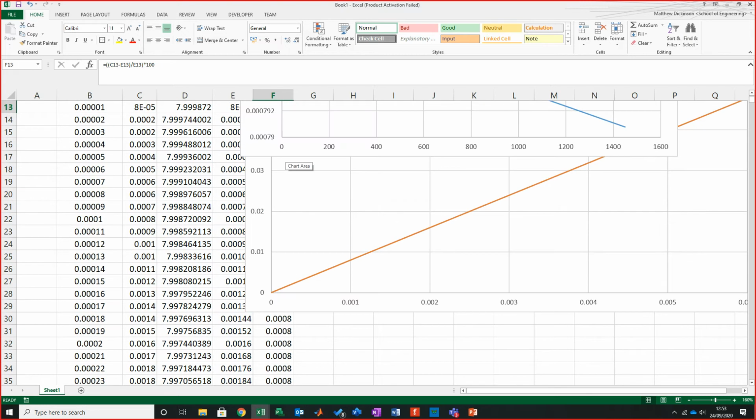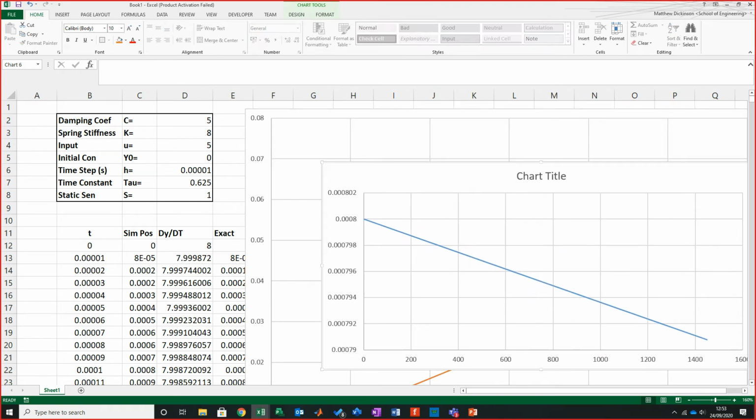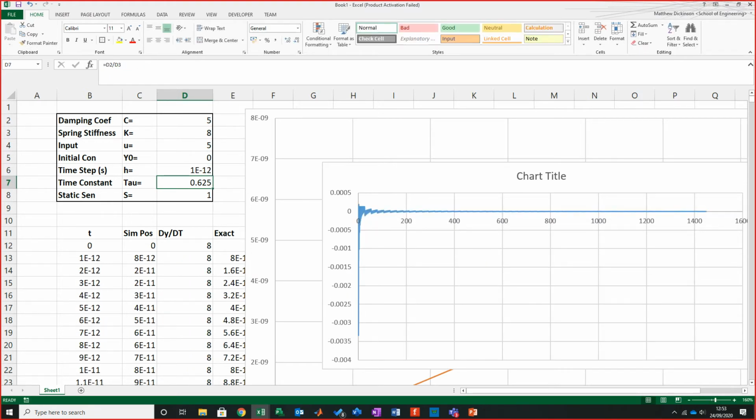So my point is, often when you're building a simulation, a system that you're predicting, a lot of people go, well, I'll make it, and in meshing this is the most common, okay, I'll go super fine. If you go extremely fine on a particular simulation, when you run it, what you'll actually find is it crashes. The amount of people I've seen sat there, and I'm not just talking students, who go, why is it crashing when I run it? It's crashing because that is what they're doing.